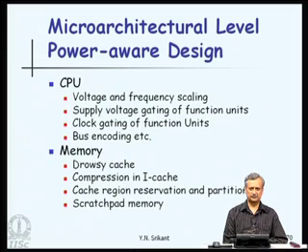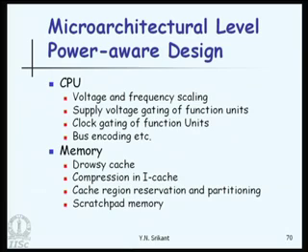What can go wrong here? It is possible that the cache line loses its data. In such a case, it is a destructive scheme, so we may have to load that cache line again after it comes back to active state. The other possibility is that it goes to standby state but retains its data. Then, when it comes back to active state, we can still access the data.